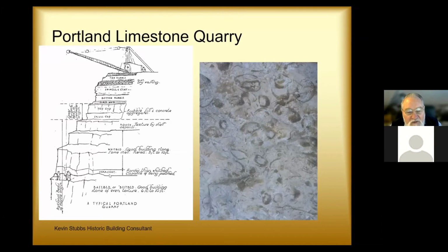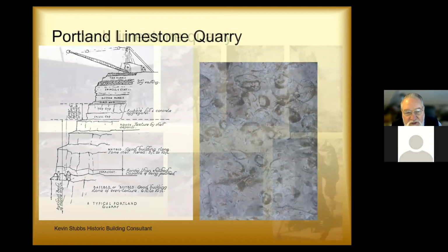It really takes a very good stonemason, or a good quarryman, to begin to recognise which beds your particular building stone has come from. The lower beds tend to have bigger shells within them. Particularly the Roach bed is an extremely shelly bed, whereas the Whit bed and the Pericot and Base beds are much finer materials.